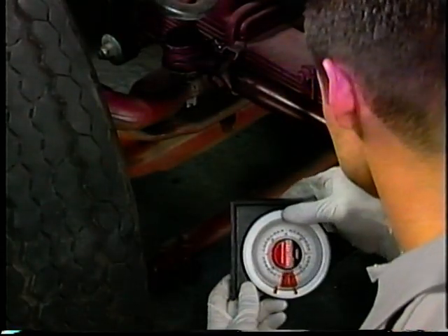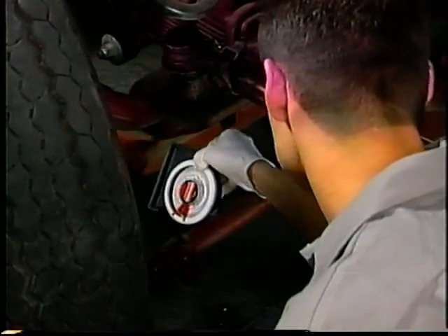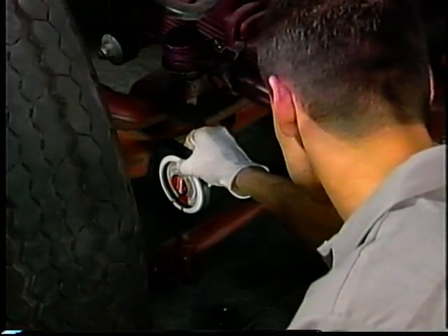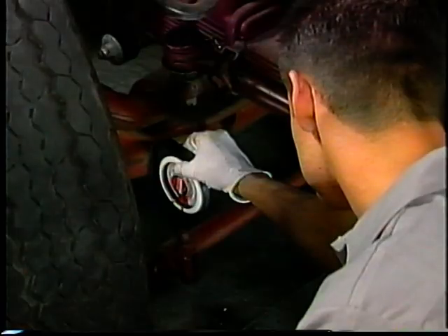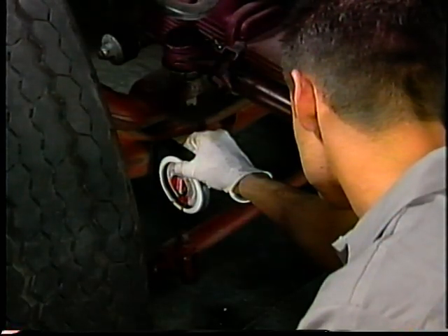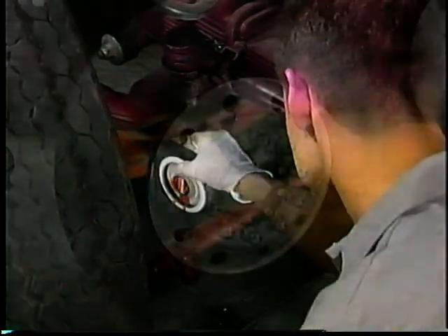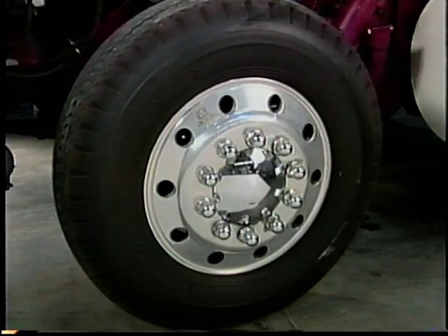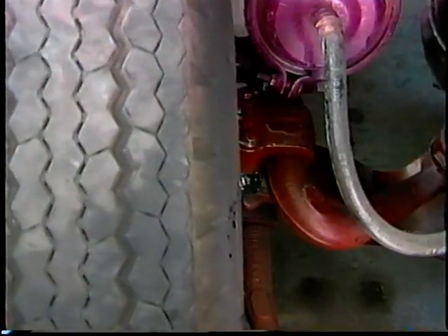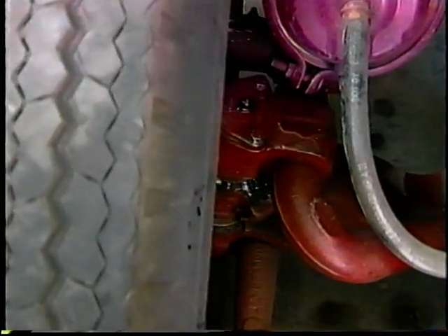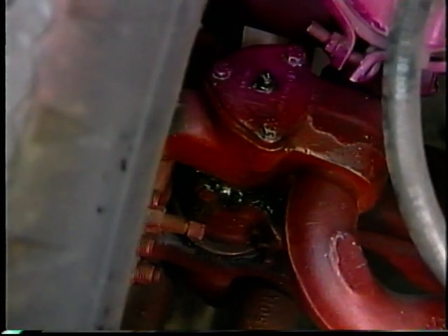A machinist's protractor can be used to determine if the axle is twisted. Bent or twisted I-beams will result in alignment angles that are off and can cause accelerated tire wear or poor handling. Kingpins, or knuckle pins as they are also called, provide the pivot points for turning the front wheels. Worn or loose kingpins or kingpin bearings can cause a shimmy or vibration while driving. Under-lubricated kingpins can cause the steering to bind.